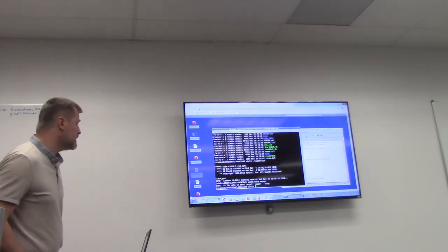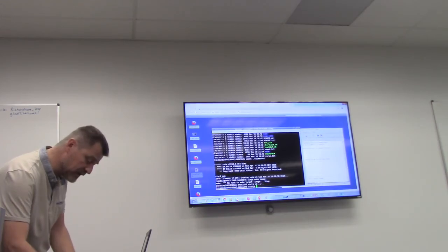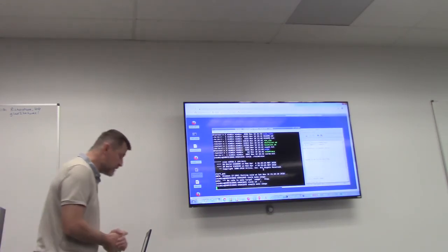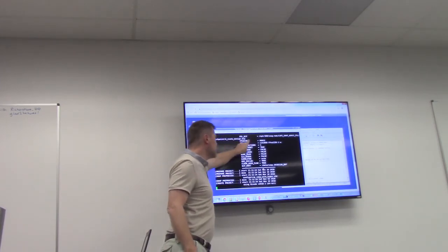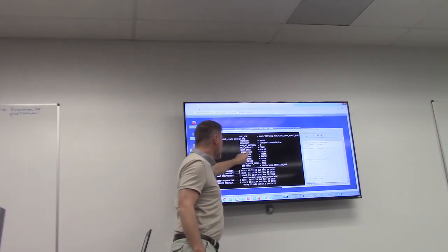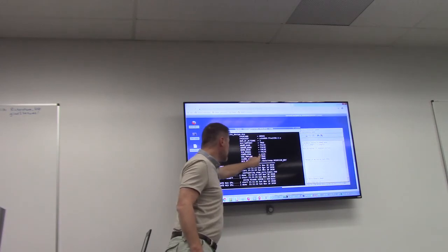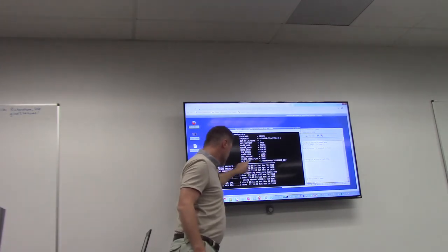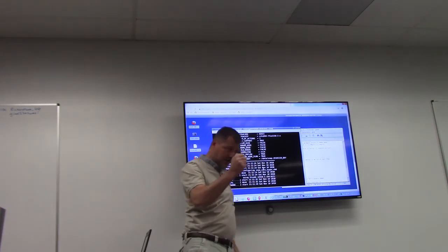And it will take, I'm not in the good directory. I need to be in the snap directory. And launch make image. The beginning will be exactly the same. It will scan the configuration file, check HLS support, yes. No RAM, no VRAM, no NVMe, no debug. Okay, simulator, yes, it's a XSIM simulator. DCP rules, remember this is where I want it to put the binary file at the end.